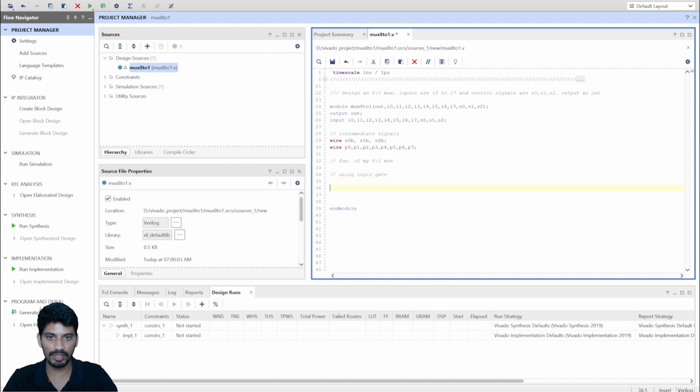So first thing is I want to get the complements of the control signals. So I am using 3 NOT gates like this. I can either give the name N1 or N2, whatever name I want, but since we are using the primitives, as I already told, for primitives you don't need to define the names. You can directly write NOT of what you want output S0 bar, right, from input S0. Done. So this will create S0 bar from S0, which is an inverted signal.